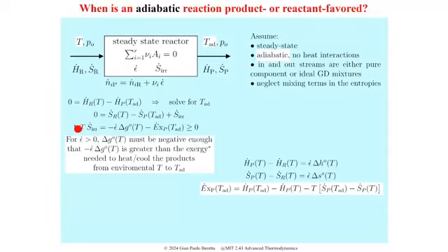And then what you get, you can split the outcome as two parts. One is our familiar Gibbs free energy of reaction term, multiplied by the epsilon dot. And these other terms, written here, are essentially the difference in the exergy of your products at this temperature from the reactants.